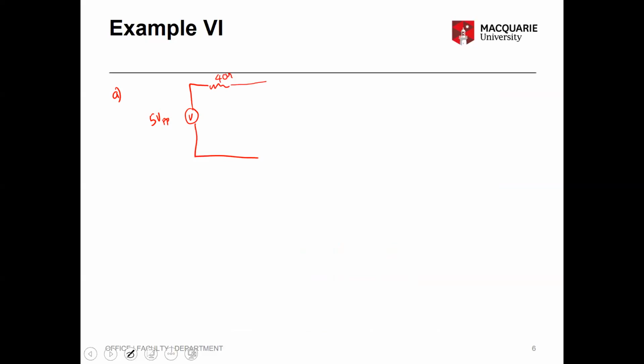For this interface 1, we then have a 40 ohm load from Z01. We don't need to talk about maximum power transfer. We have 40 ohm, and if this is 5 volt peak to peak, the voltage across that is divided in half because it's the same impedance. So that's going to be 2.5 volt peak to peak.